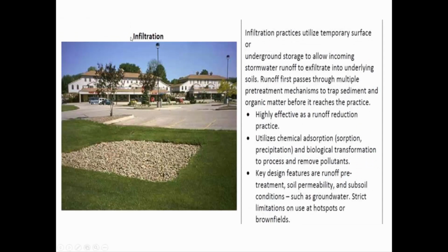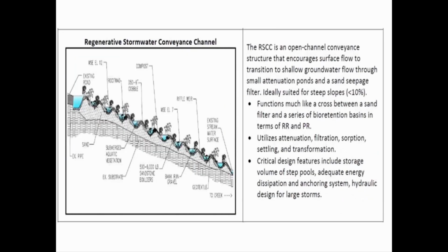Okay, here just promoting new ways of having additional infiltration. What this is showing is a local pond in a commercial development where the runoff from this parking lot is going towards the pond, and what they've done is they've dug out the center of the pond and amended the soil there. Instead of just having whatever soil it was initially, they've put in gravel where the water can seep down to the subsurface more easily.